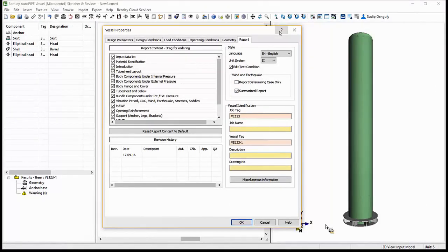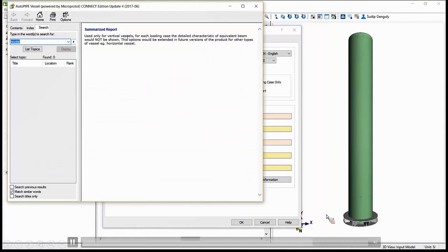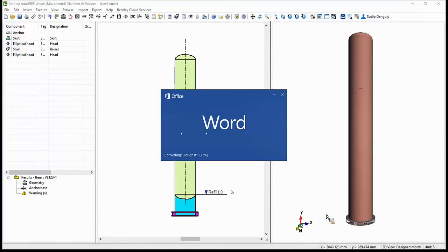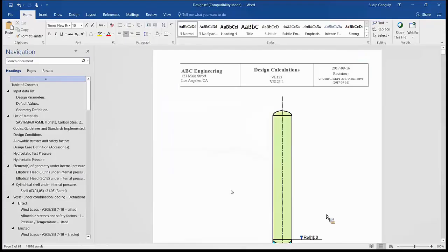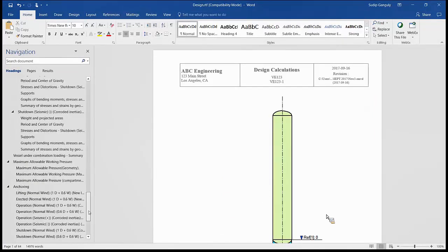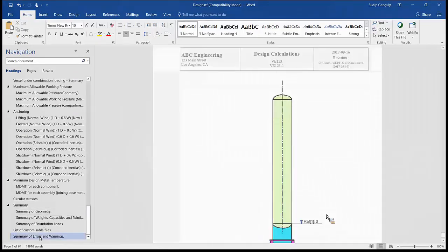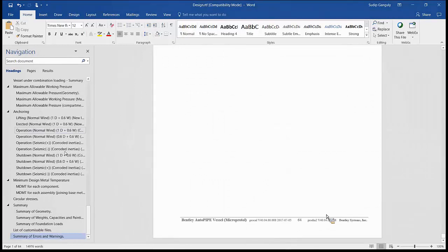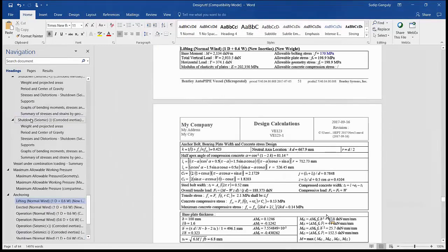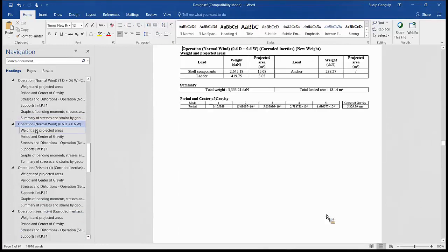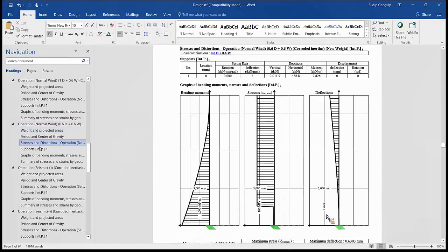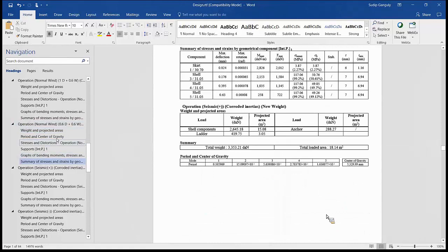There's also another section called summarize report. So what it does is it doesn't show the detailed characteristic of the equivalent beam. So there are cases where you want to do an advanced analysis and you want to look at much more detail than what normally engineers would review. So that's why we end up putting everything in the report. But there are these options available for summary reports or report determining cases. So in this summary report, you see all the load cases, but the details of the stresses and equivalent beam calculation method reports are not shown, just to keep the report simple and light.